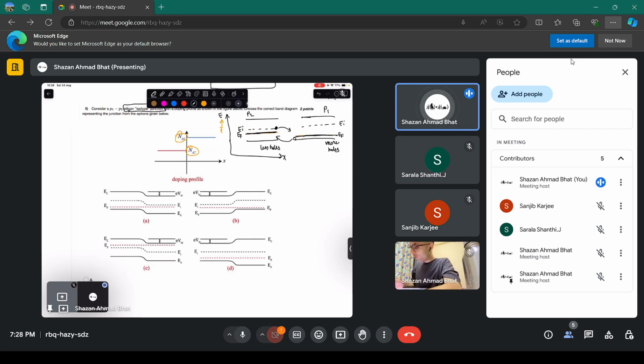So when there will be motion of electrons, because electrons are anyways going to be present in the system, although they will be less, they are going to be present. Because if it is totally p-type, then you know that the electrons will be minority carriers, but they are there. Minority carriers means you can find the concentration to be equivalent to Ni squared over Na, and here, let's say it's N1.